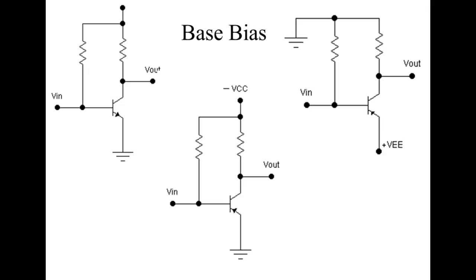Yeah, so temperature goes up, beta goes up. And beta goes up, what current goes up? IC goes up. Okay, if IC goes up, then the transistor is going to get a little hotter, right? Even if beta goes up, the transistor drops less voltage, but remember, current is more predominant in power because it's I squared R. So even though the R of the transistor drops a little bit, current varies by the square. So current goes up, which causes the transistor to get hotter and then causes beta to go up, which causes current to go up, and we refer to this as thermal runaway.